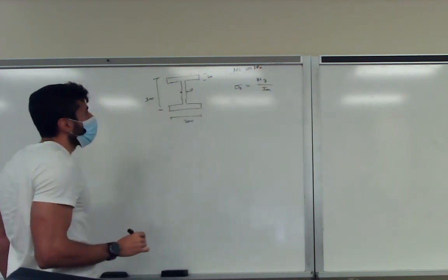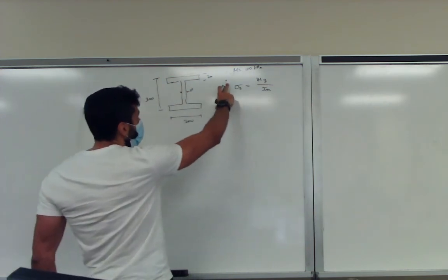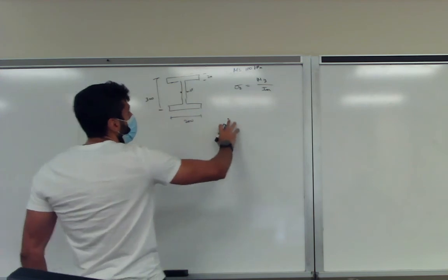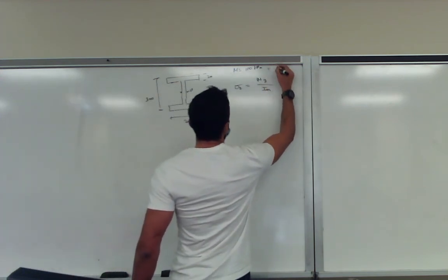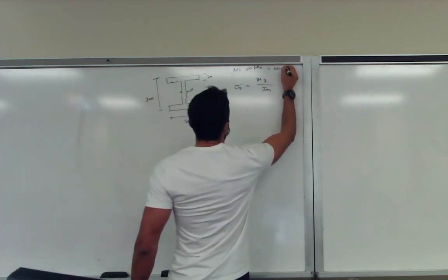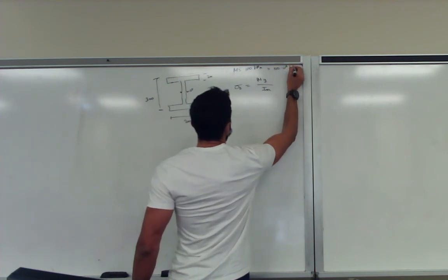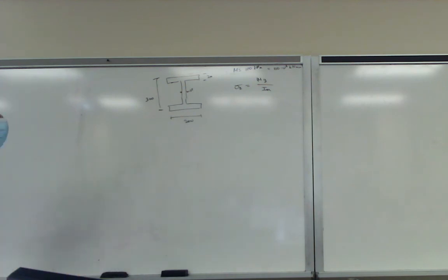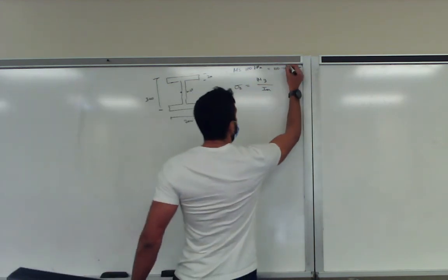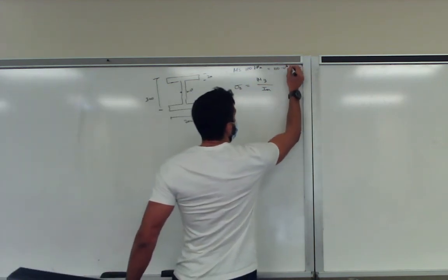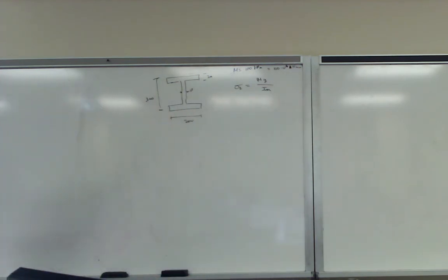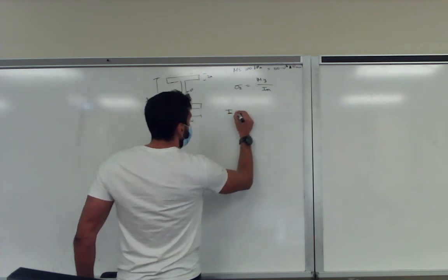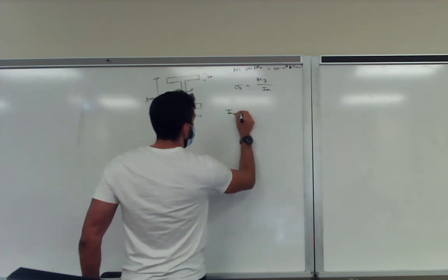Now then, what's always useful to do, always convert to the same dimensions which moment of inertia is in, and your location y is in. So this becomes 10 to the power 3 kilonewton millimeter. So you just multiply by 3. And if you want to go in Newton millimeters, then this becomes 10 to the power 6 Newton millimeter. So the goal is to determine the moment of inertia, since that's only, say, the difficult part in this case.